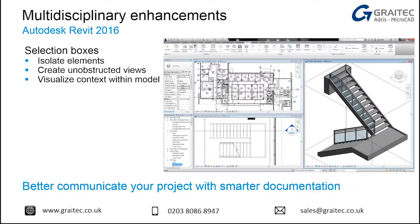Section boxes, I quite like this as a little feature. We've always been able to create these manually, but now we can do it by an object. So we can actually physically select an object and ask it to put a section box around it. So we get a 3D representation of an object. This is really useful when you're putting drawing sheets together and you're trying to make sure that you get a full understanding of how something's actually working. So it's a much, much better way of just communicating our design intent, if you like.